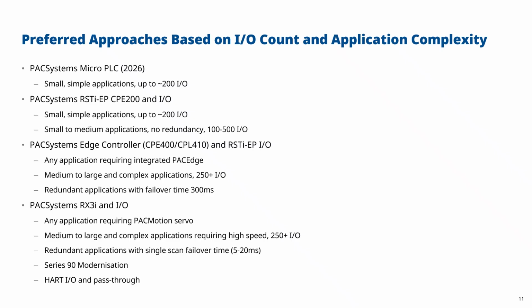The PACSystems Edge controller with RSTi-EP I/O, ideal for any application requiring an integrated PAC edge. Also suitable for medium and large to complex applications from about 250 I/O upwards. And again, for redundancy, we support that failover time of 300 milliseconds, so a good option for redundancy applications.